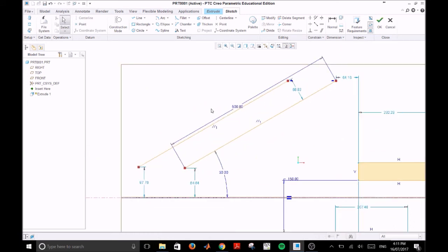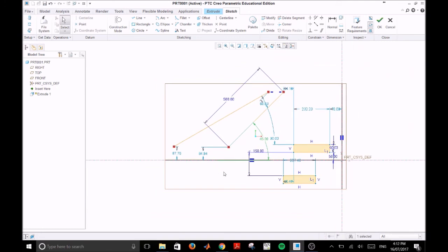Now, as I mentioned before, often by default, Creo adds constraints. Sometimes these can get a bit confusing or can be unnecessary. You can simply select those, then delete them, and the constraint is removed. And if I change this back to 45 degrees, the second line would not follow suit. So previously, we've looked at symmetric constraints, equal and parallel constraints. The last one we'll look at in this video is tangency.